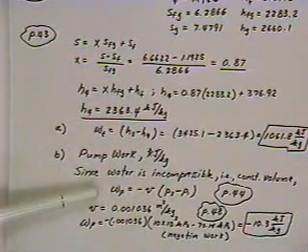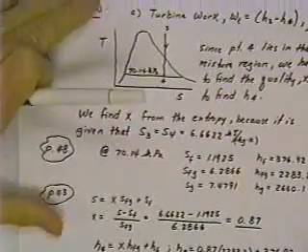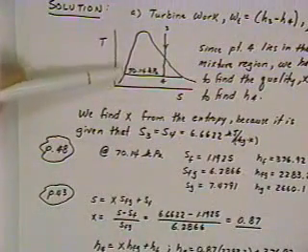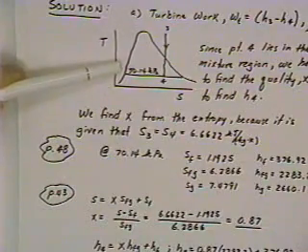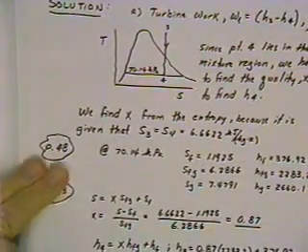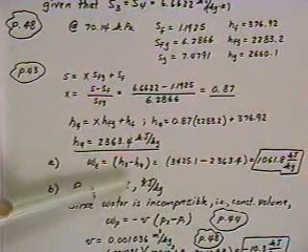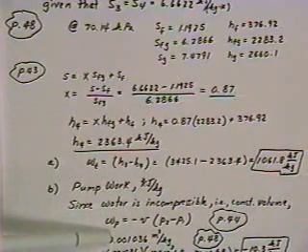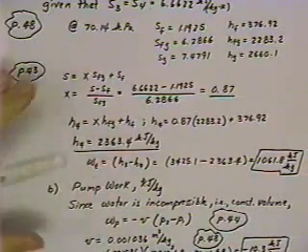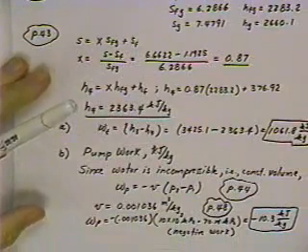And so what we're after then, if we go back up to our condition here, entering the pump, and we're pumping from point 1 to point 2 from our original diagram. So we look at the specific volume of water, 0.001036 cubic meters per kilogram.